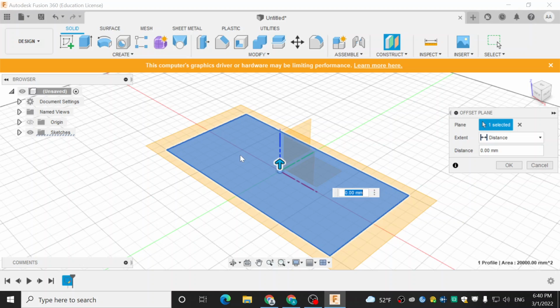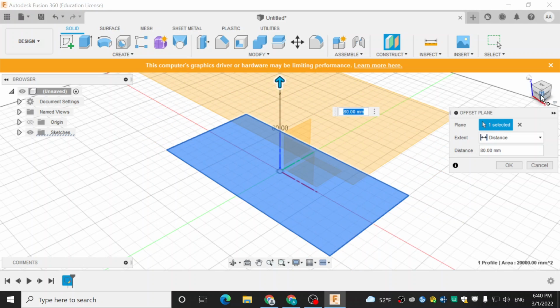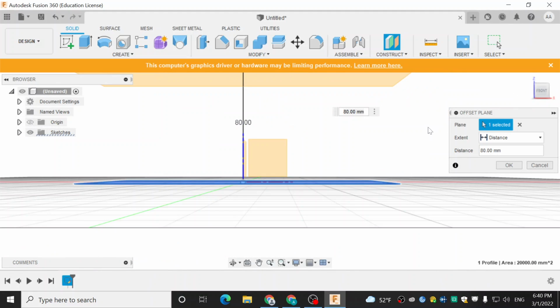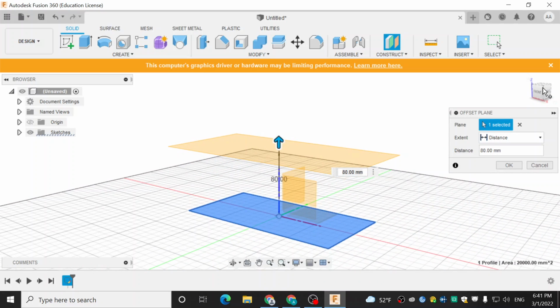But instead of extruding, you can take this plane and bring it above or below the pre-existing planes. This is really helpful if you haven't necessarily started creating a lot of parts and you need more faces above you. That's going to be even more important for something called lofting, which is what we're going to go over mostly today.